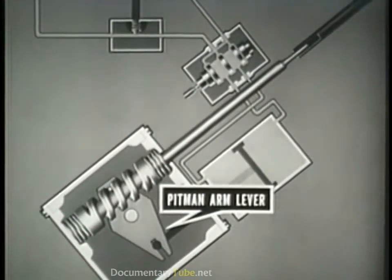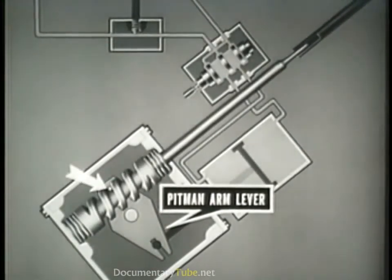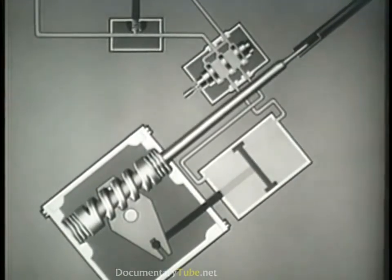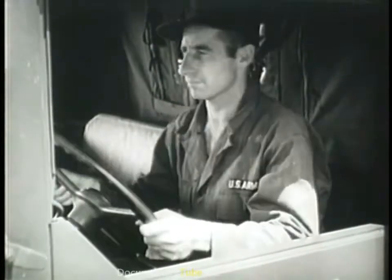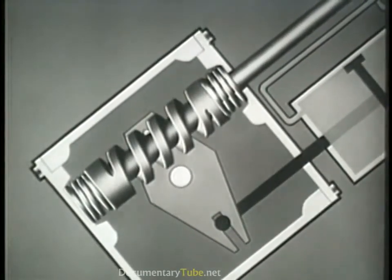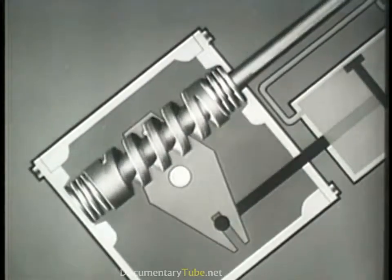The pitman arm lever, which actuates the pitman arm, has one end fastened to the piston rod, the other in mesh with a groove in the steering cam. When the steering shaft is turned, it requires a greater effort to turn the Pitman arm shaft and lever than to compress the springs at either end of the cam. This is so because the Pitman arm shaft and lever are connected to the front wheels. This action causes a cam spring to be compressed, allowing the cam to move up or down, depending on the direction that the steering wheel is turned.